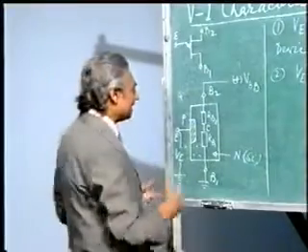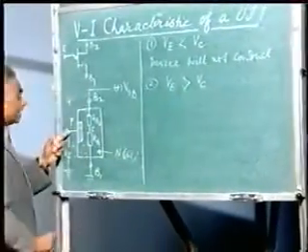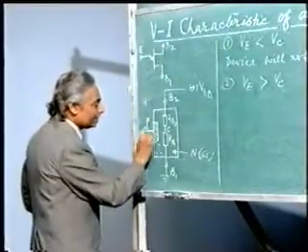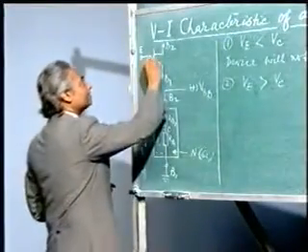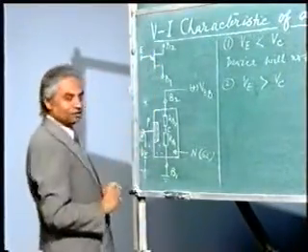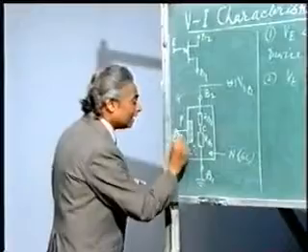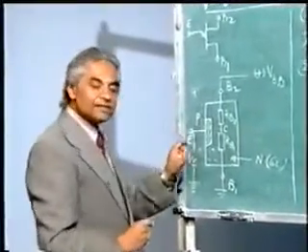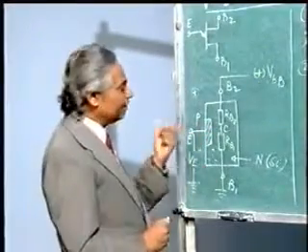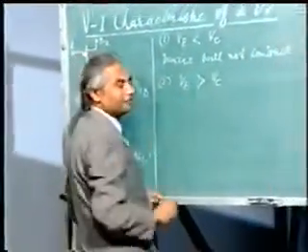So it is very clear that when this starts conducting, in this condition VE greater than VC, the diode starts conducting. At that moment the positive holes from this p layer will start drifting towards B1. That is why this arrow has been given towards B1 and not towards B2. So conduction starts taking place, and they make electron hole and positive hole pairs. So resistance will reduce, further it will reduce, and naturally the conduction will hold, it will remain continuously conducting. So this is the condition when VE is greater than VC.